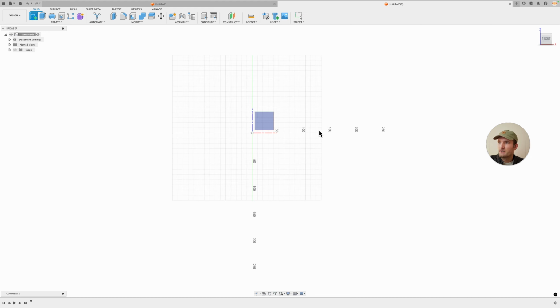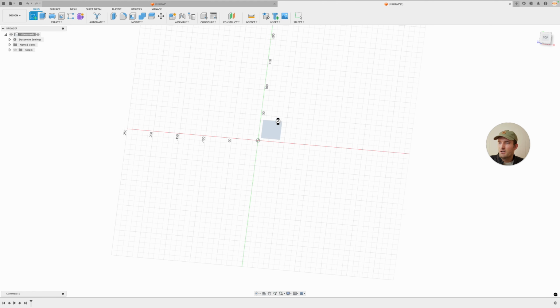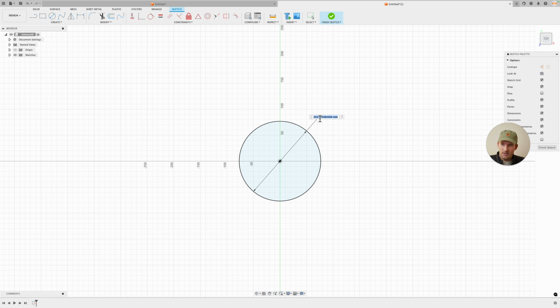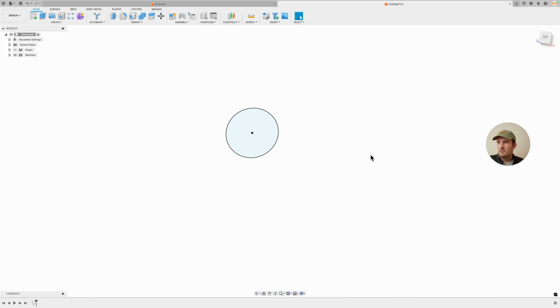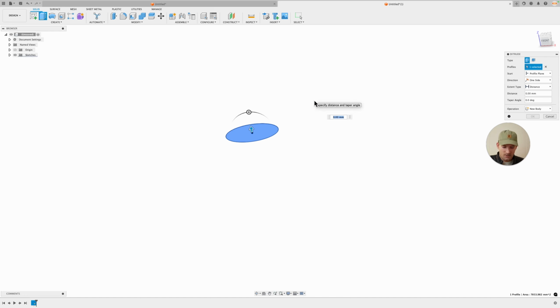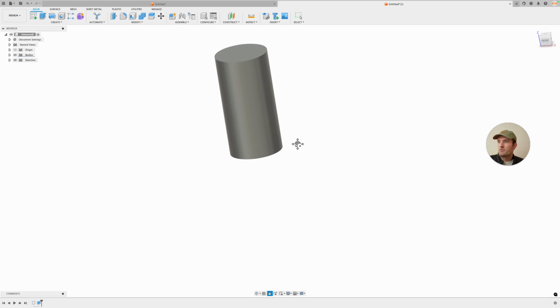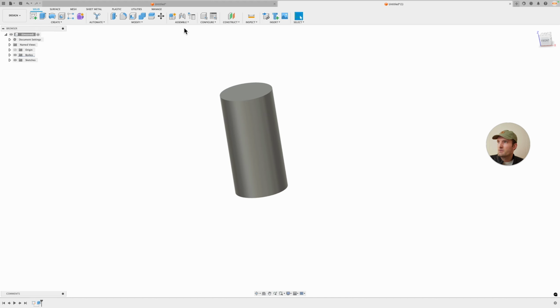So now we're going to create a sketch. I'll just use the top here, make a circle, and our diameter here is going to be diameter, which is 100. Finish sketch. Now we're going to extrude. So click E, and we're going to extrude by height, which is 200. Click enter. Actually, let's go ahead and shell everything out. So shell here, make it 2. You could also make that a parameter if you wanted to.